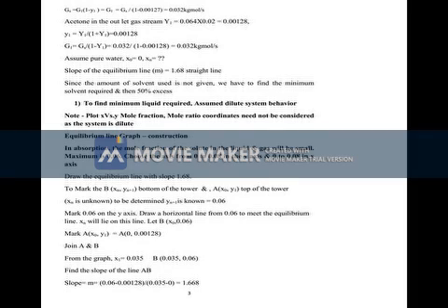Next, you have to find out the column diameter from empirical equations. By now you would have become very familiar with these empirical equations. Then the downcomer segment area and tray layout. The tray layout means how many bubble caps or how many sieves are to be there, and how they are arranged. Pitch. What is pitch? Pitch is the center to center distance of two sleeves or two slots. Then tray thickness.